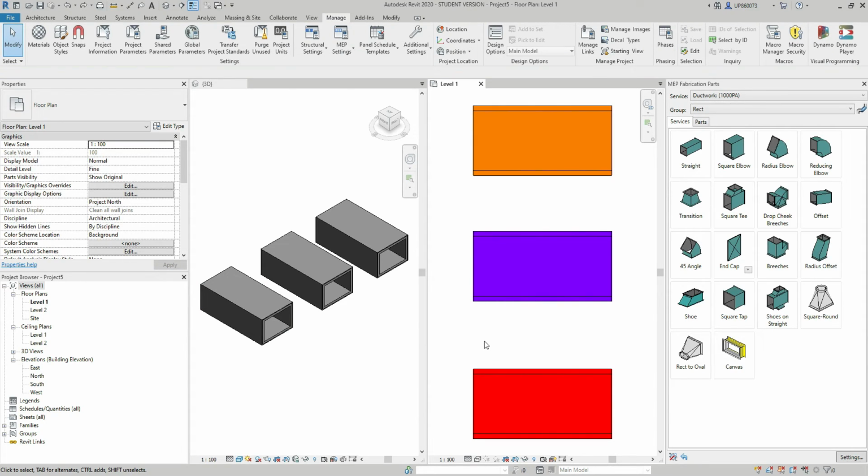The option with parameters and filters is much more efficient as opposed to the filled region option. You only need to create parameters and filters once and use it in your project. If you decide to update the duct size to make it wider or narrower, the color changes with it.